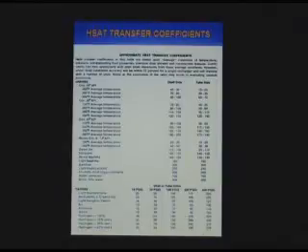I apologize. This shows you the typical heat transfer coefficients that you might expect for different fluids. Here for heavy oils, you're on the order of 15 to 25. The higher the duty, basically what that means is you have a poor fluid for heat transfer. It means you're going to require more surface area to perform that duty. And when I say duty, I mean BTUs per hour, how much heat you can exchange between streams.